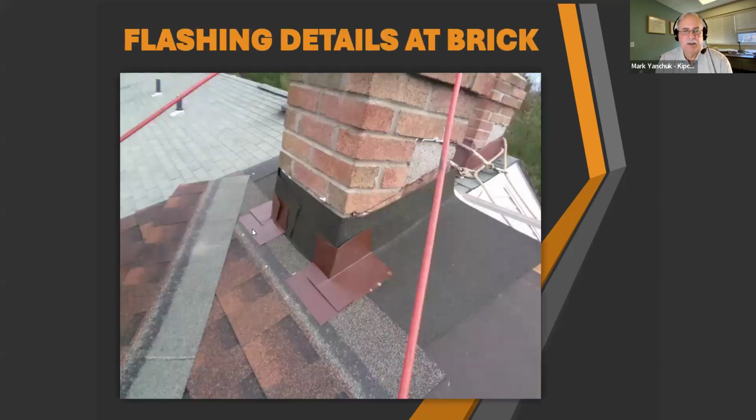You'll have flashing. There are two types of chimney chases. There's the solid brick ones, and then there's the wood. So this will require special counter flashing that has to be put over the flashing after it's installed. You can see that there's a reglet cut here for the counter flashing, which will look something similar to this.